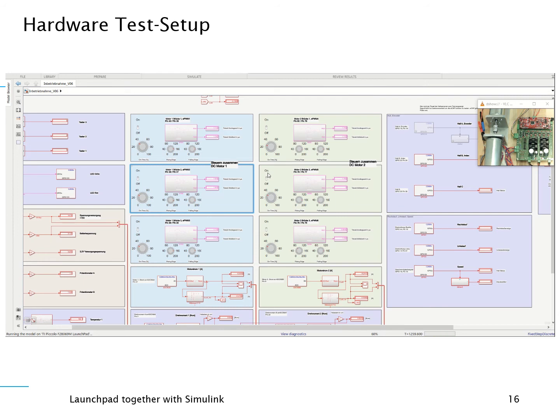As I use the MOSFET driver, if the high side is turned off, the lower MOSFETs will always be turned on. So this means if I switch the high side MOSFET, the motor starts turning. Again, you see a little delay in the USB camera from the moment I turn it on. Maybe you hear the motor running, synchronous with when I turn it on and off.